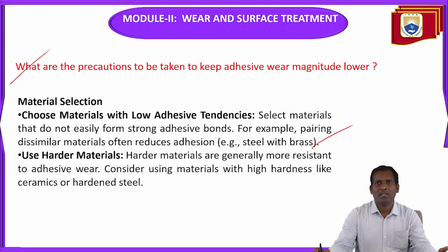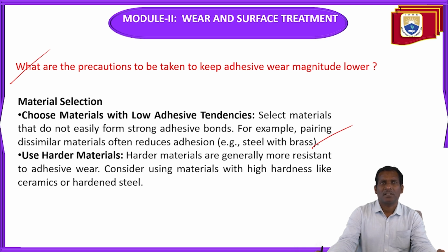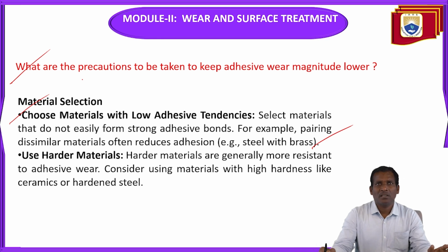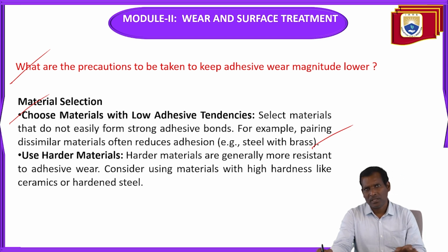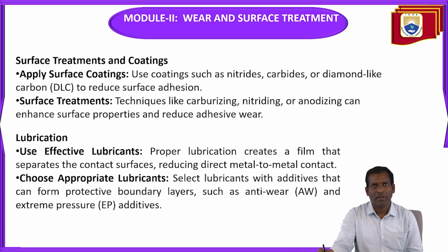Consider using materials with a high hardness like ceramics or hardened steel. So this is the precaution you can take to keep adhesive wear magnitude lower: material selection and use of harder materials. And surface treatments and coatings.